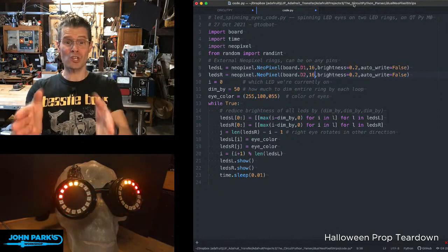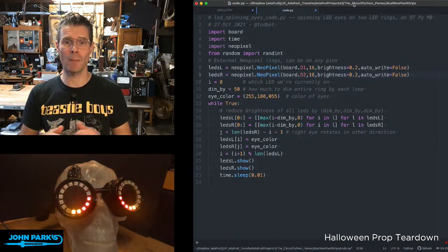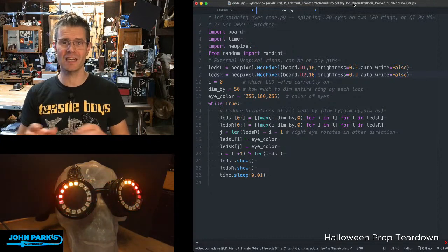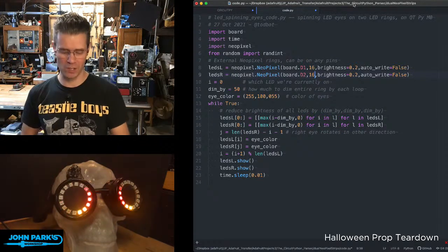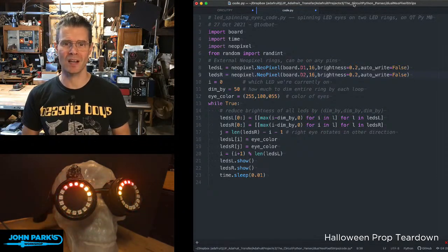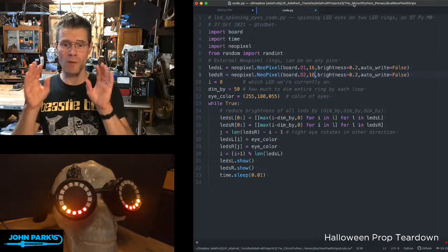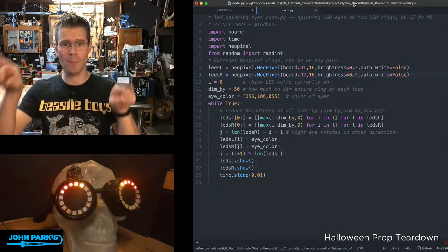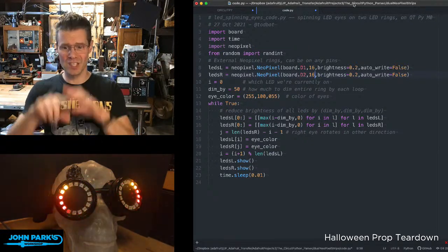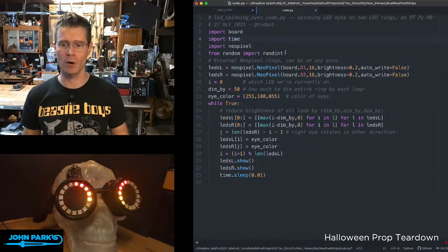We'll start this from scratch. For the CircuitPython Parsec today, I wanted to talk about controlling a pair of neopixel rings from a single microcontroller. So this is a pair of prop goggles that I have, and I have two 16 neopixel rings. It's being controlled by a Gemma, which is an M0 based microcontroller, and I have a little LiPo battery tucked inside of there. This code from our good friend Toddbot allows us to do a very succinct bit of code that gives us this nice spinning neopixel effect on two separate neopixel rings, and you can see they're going in opposite directions.